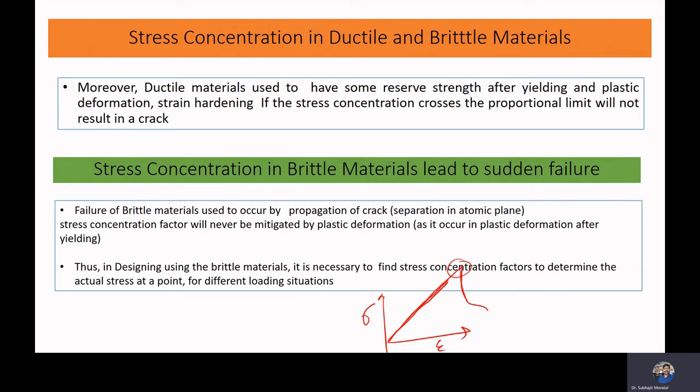So stress concentration becomes a big factor here, and the stress developing in that zone never gets a chance to mitigate, because once it reaches the ultimate stress, failure occurs suddenly. So in the case of brittle material, stress concentration is a big factor.